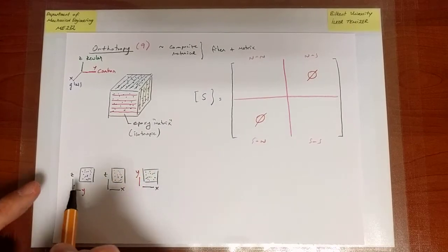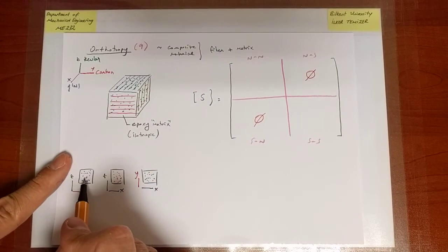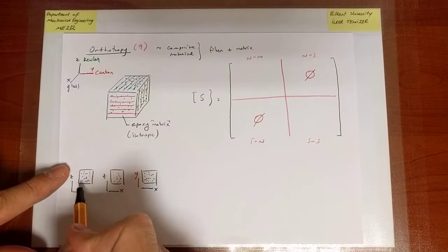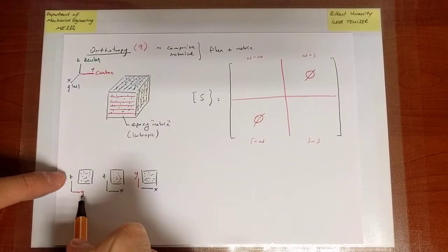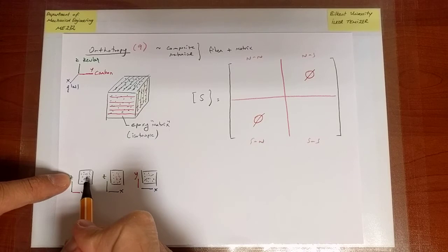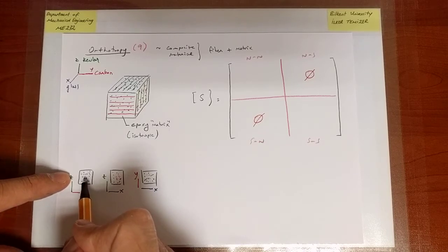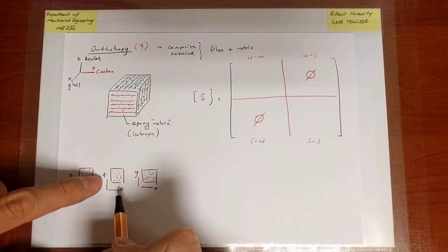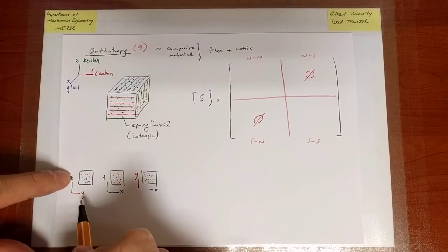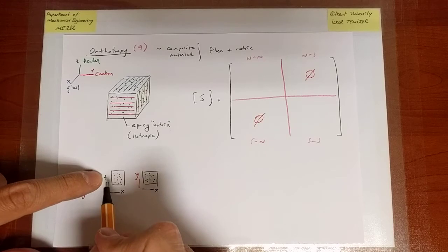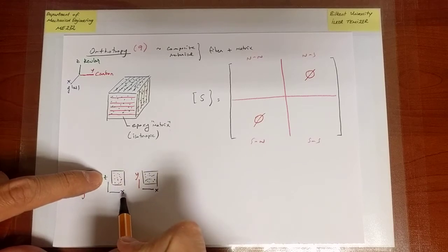So now if I shear this square, I will be trying to change the angle between Kevlar and carbon, and in between there's some glass. So there will be some shear modulus associated with that. If I want to shear that picture, I'm going to be shearing not Kevlar and carbon, but Kevlar and glass. So there's going to be another shear modulus probably, and they're not going to be the same.